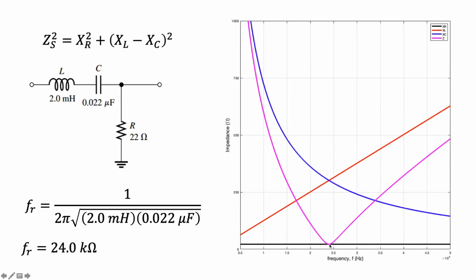At the resonant frequency, XC is equal to XL, and therefore Z is equal to R, as you can see from the figure. The current and the voltage across R are also maximum, entirely due to the resistor. Above the resonant frequency, XL is greater than XC, so the total impedance follows from XL and becomes linear as well. The current then slowly decreases.